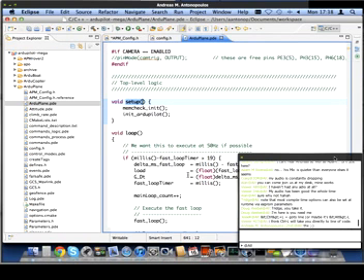If you're interested in looking at it, it's based on a little canary system where it basically sets up some known bytes at particular locations in memory and then periodically checks those bytes to see if they've been overwritten. And that way it's able to check, for example, for stack usage or interrupt usage or any other form of memory usage. So that's what memCheckerInit does. It sets up those canary bytes in memory, and then there's a regular check later that checks how many bytes have been used, and that's reported to the ground station via the meminfo message, which then tells the ground station exactly how much memory has been used.